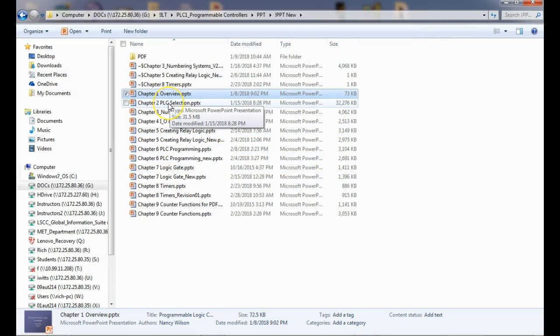I think they talked about scan. Everybody else okay with scan? So what is a scan? A PLC scan? It's the time it takes to go through what? The program. And how does it work? Top to bottom, left to right, right? Inputs. Not yet. Input, process, output. You understand that? It scans inputs first. Then what does it do? Then it processes the instructions, and then it develops outputs based on what the instruction says.